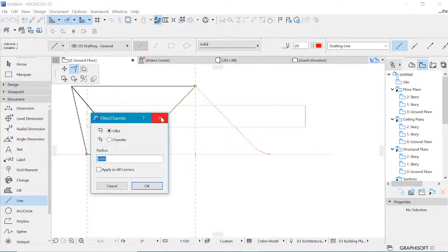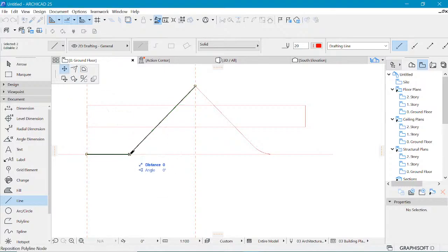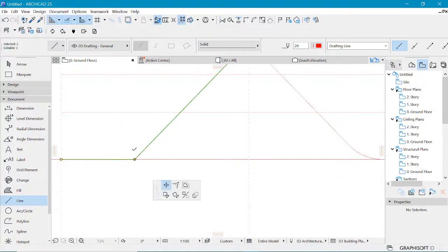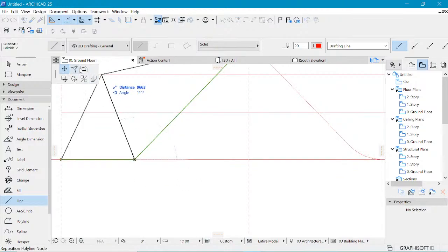Some people don't know how the pet palette works, so they get a little confused. Whenever you click a node, this thing pops up, this is the pet palette, and it can be moved anywhere. So from it, you choose this second option, which has fillet, stroke, chamfer.